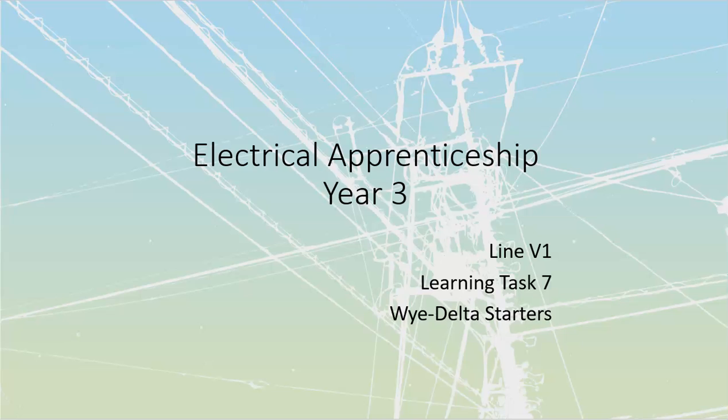Now, this is base three-phase theory. You should be quite familiar with this from everything that we covered in the very first learning test that we entered into in third year here, which is really that when we take identical loads and reconfigure them from Delta to Y, or from Y to Delta, we're going to see a change in the total amount of kVA that they are going to deliver. Note that this is only something that applies to loads, right?